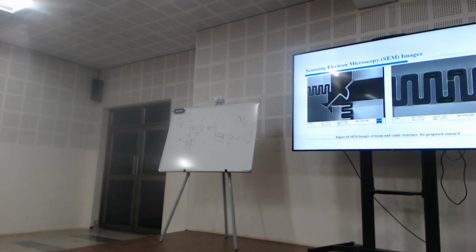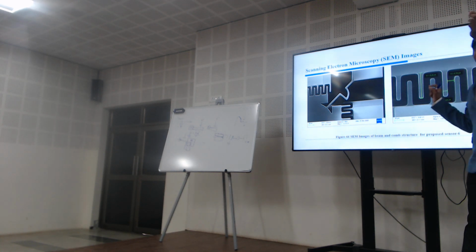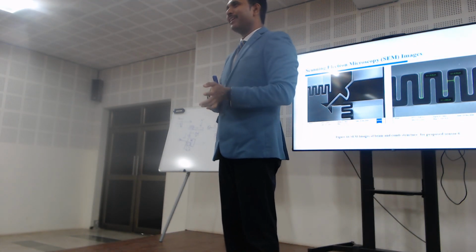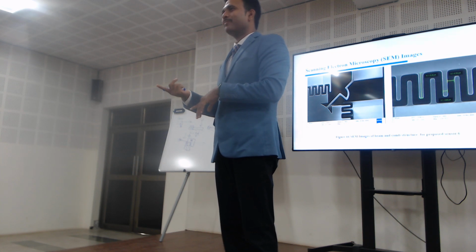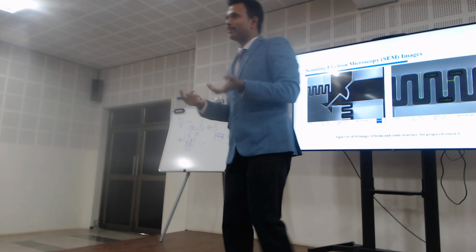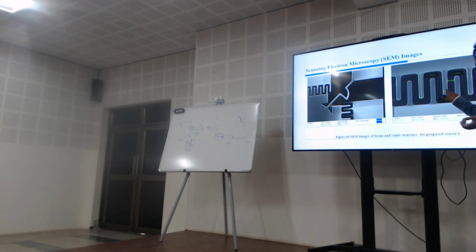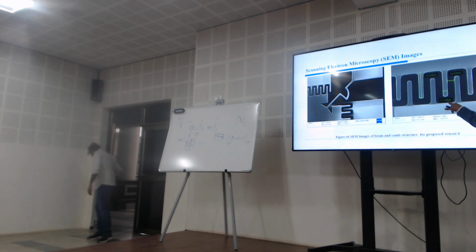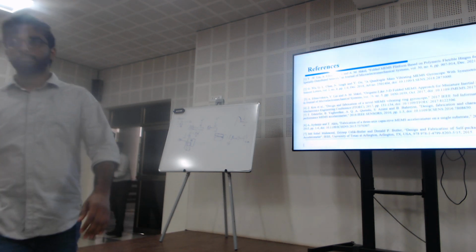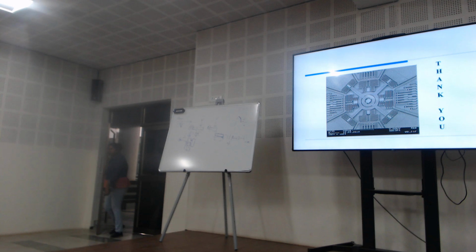See, initially I gave 1 point also. Whenever we fabricate, whatever simulated result we are getting, after fabrication it will change, completely. Because for MEMS, the minimum size is still 5 microns only. I used 5 micron thickness minimum. But after fabrication, how much am I getting? 4.52. Now can I compare with simulation? Not possible. I need to go for simulation again, then only can I compare. So these are some differences I had noted initially.